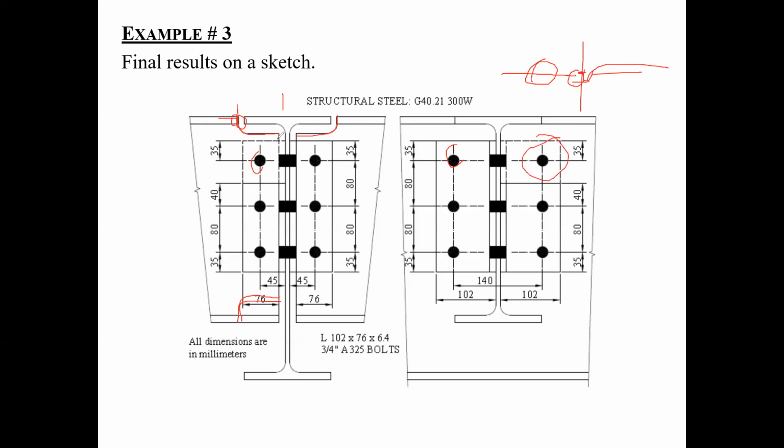So what you do is you cut out the angle where the bolt that you're going to be using to hold the first beam in place is, so that when you put the next beam in place, you can put all the other 5 bolts and connect them together back to back. That's the typical erection connection you have for this situation only. I'm showing this example more for your general information, and if you can't follow it, don't worry about it. But if you're interested in knowing how to do it, go back and review it a little bit more carefully. And if it's still not clear, I'll be more than happy to review it with you. And I think that's it.